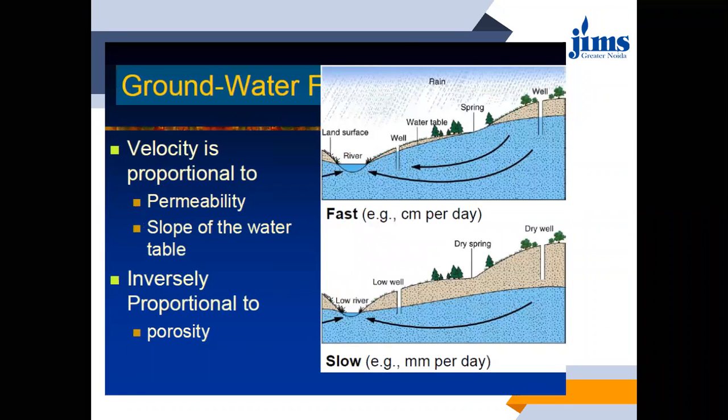Then another subdiscipline is groundwater recharge. So how does this groundwater recharge take place? As we have discussed, whatever form of precipitation is there, it will ultimately come on the ground surface itself, and from there, due to permeability, groundwater flow, porosity, all these properties will allow any form of precipitation to percolate or infiltrate into the ground surface.